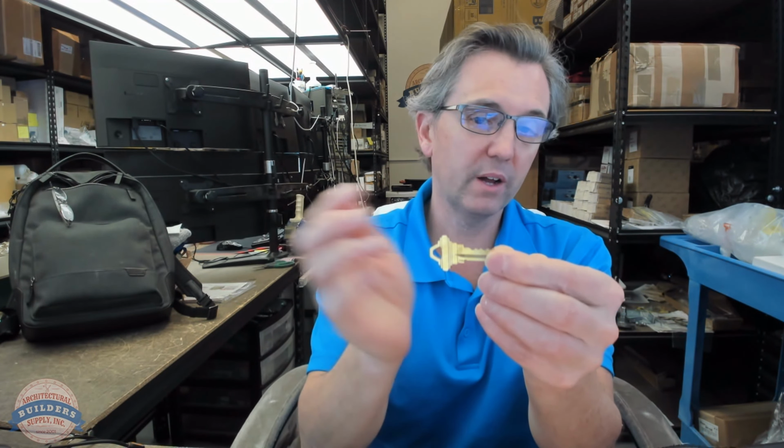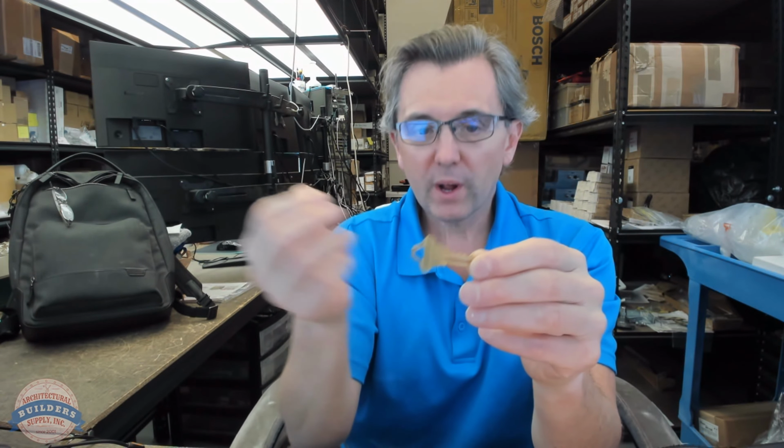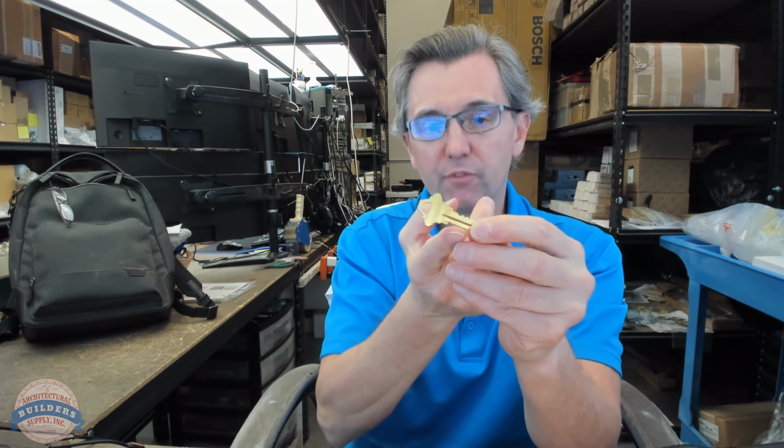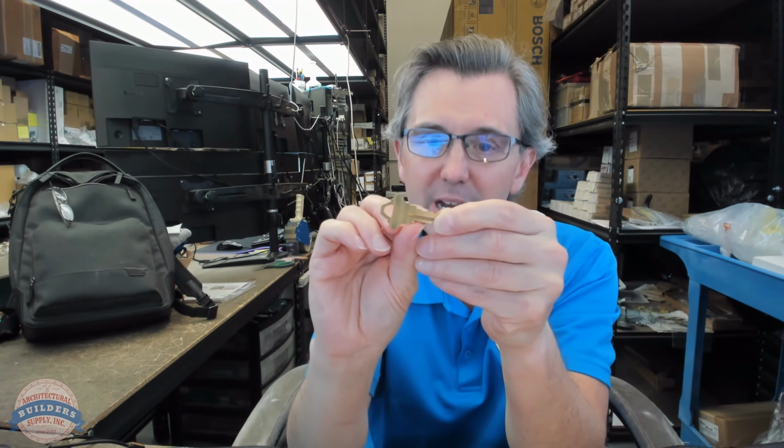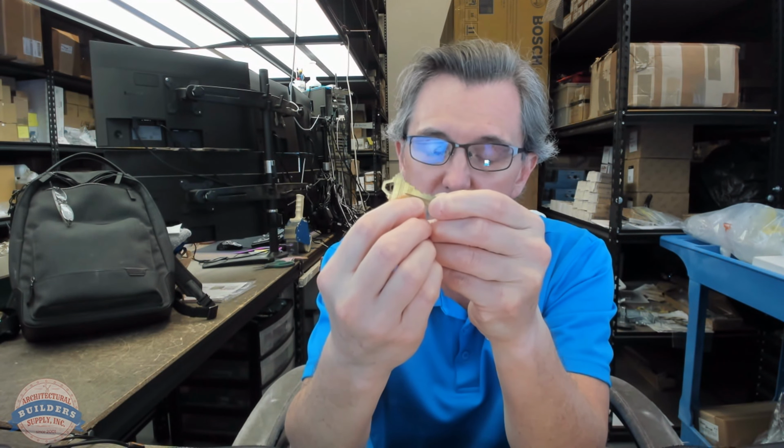Number two, the depth. How deep a cut is versus any other depth cut in that manufacturer system. So if I were to cut 5 on this, a 5 cut, 5 is an arbitrary number, really. 5 translates to a very specific dimension from the bottom of the key to the bottom of the cut, or what's called the root depth. Okay, that's the second thing.